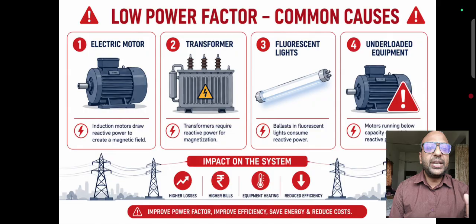Now we come to causes of low power factor. Main causes are induction motors, transformers, fluorescent lights, motors that are overloaded or oversized for the job, and long transmission lines with poor voltage regulation. These all draw excessive reactive current.